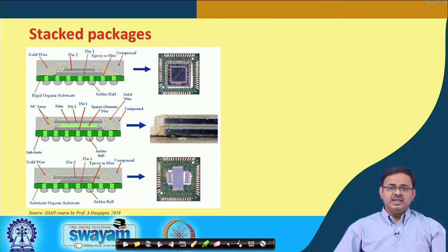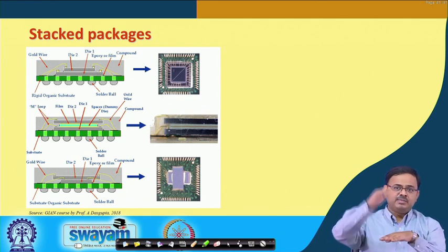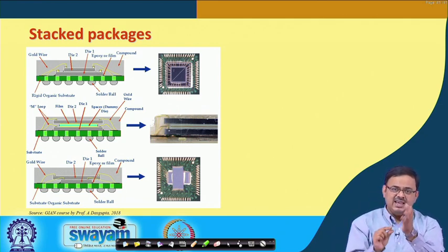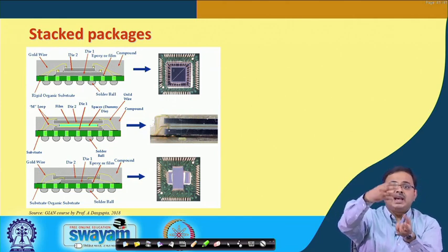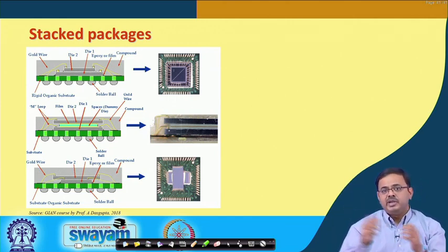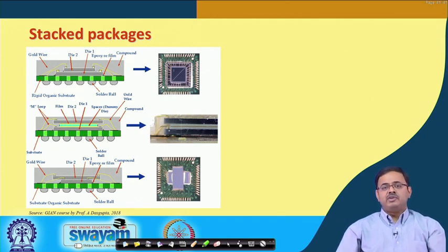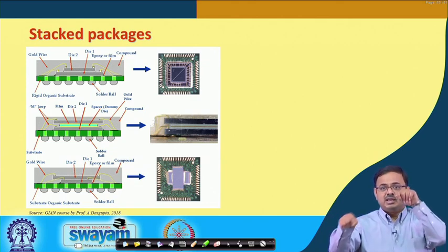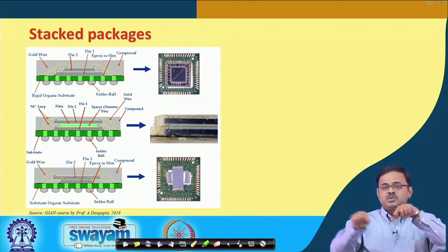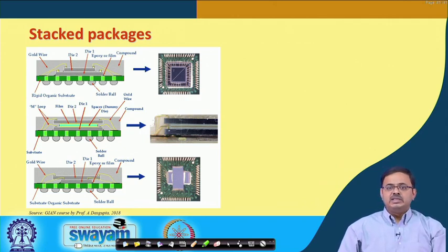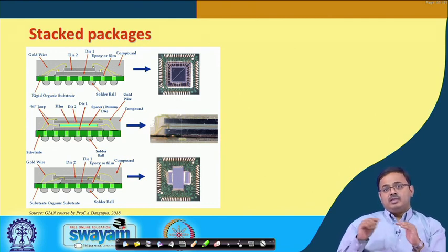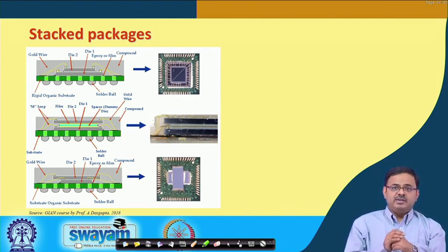The thermal engineer will say that is the worst design. You are lining up the hotspots, I will just have a single area along the 3D stacking where the entire heat will be generated. It will be a nightmare for me to dissipate the heat, and in no time will your temperatures just shoot up. If you want a good thermal design, and you have two dies, place these hotspots farthest away from each other. Now, that would be a very good thermal design, but not the best electrical design, rather probably among the worst electrical designs. So, how do you come to a compromise?